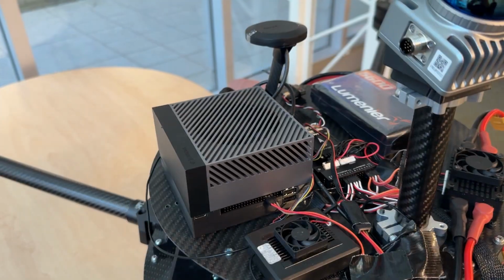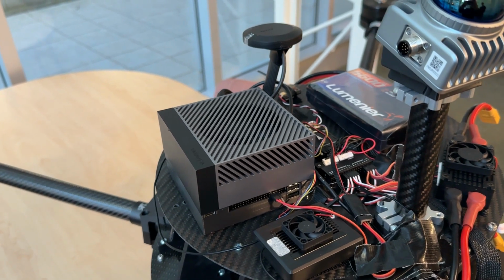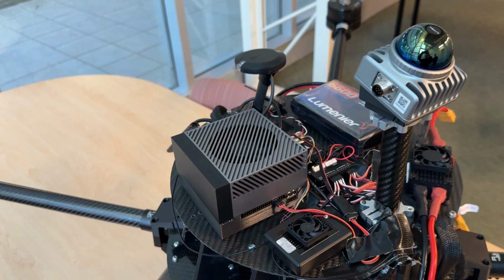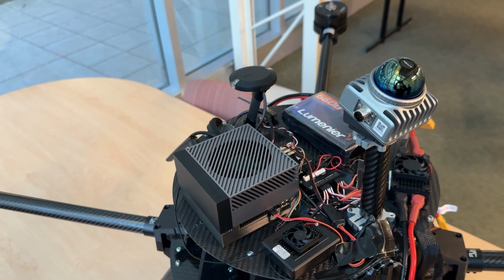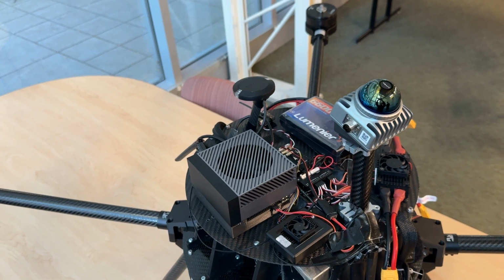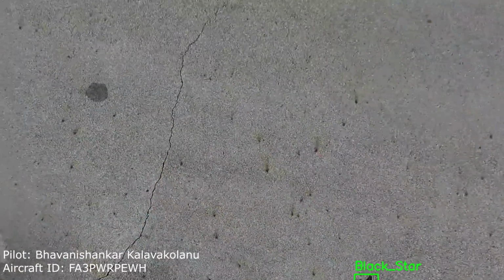To run these object detection algorithms in real time, the team decided to employ a Jetson Orin AGX. This was chosen over various alternatives, including other Jetson models like the Jetson Xavier NX or Jetson TX2, as well as general-purpose CPUs like the Intel NUC products. While these alternatives offered respectable performance, they lacked the specialized hardware acceleration and computational power required to efficiently run large YOLO V8 models in real time.